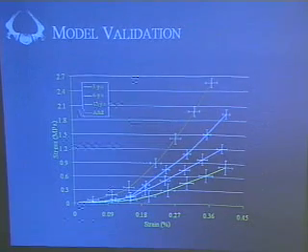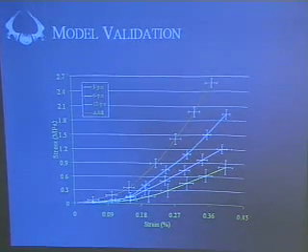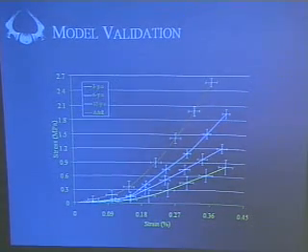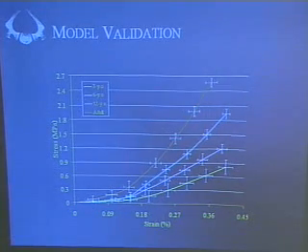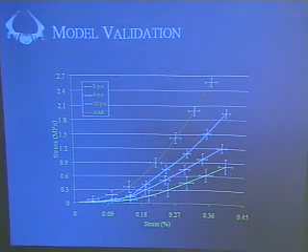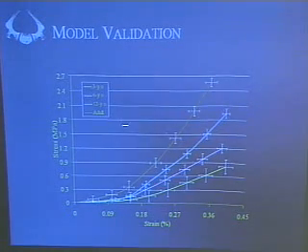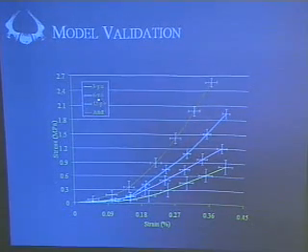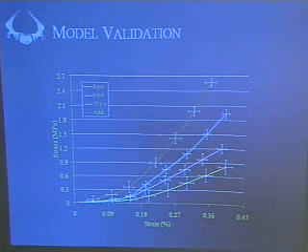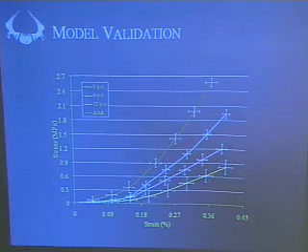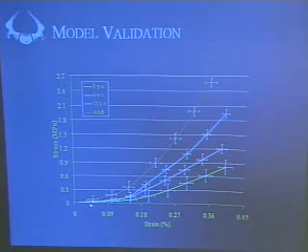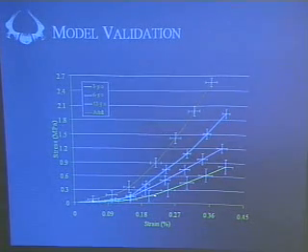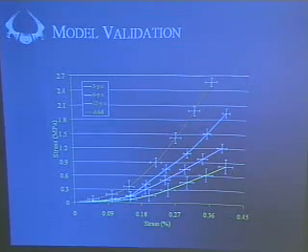So now I'm going to jump to a validation of this model. What I did is I took the tensile stress-strain relationships from all the specimens that we had, and I came up with adult, 12-year-old, 6-year-old, and 3-year-old mean curves. So I had the mean and standard deviation of each of those experimental tests that we ran, and you can see those presented right here.